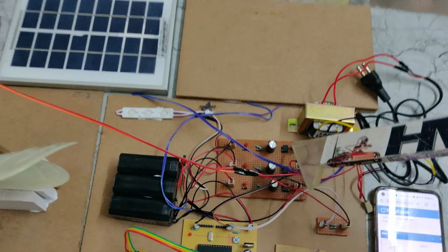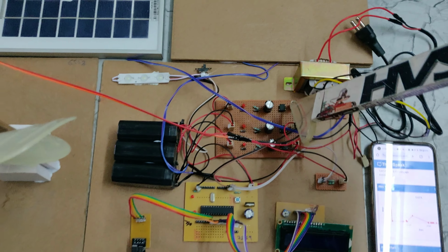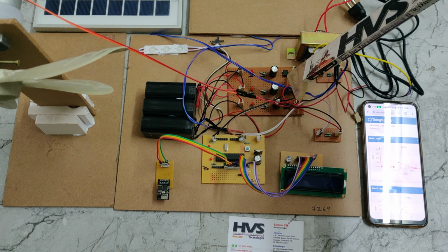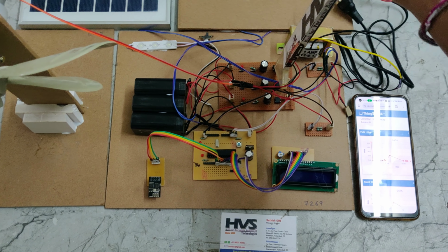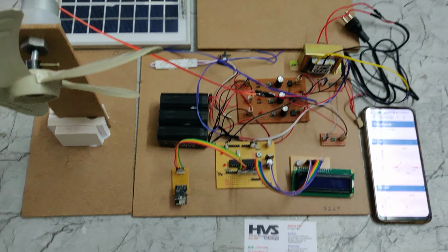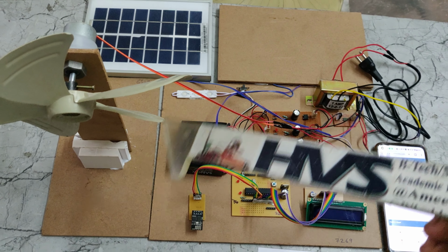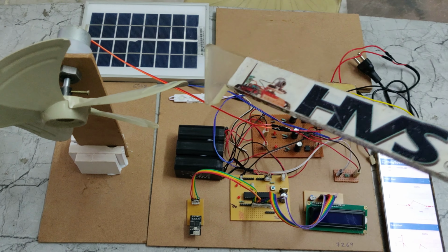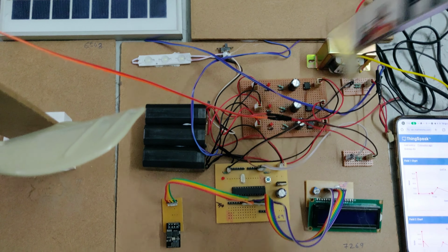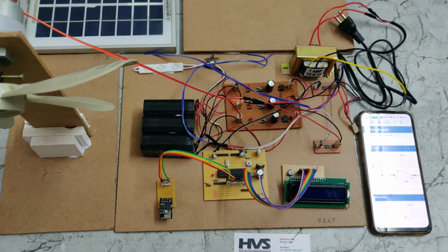Here we can see these three charging circuits look the same. Each charging circuit consists of a DB107 rectifier, which is a full wave rectifier that takes AC inputs and provides DC outputs. But here we are using DC sources only, so the rectifier's purpose, when we provide DC inputs, is to act as a polarity corrector.